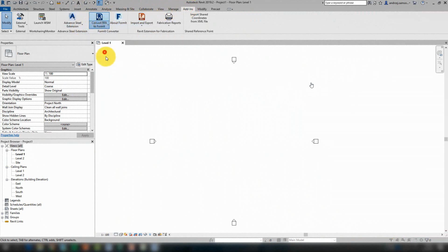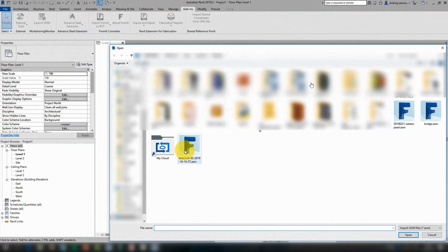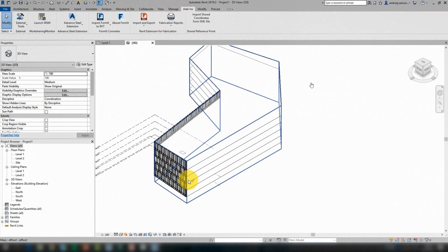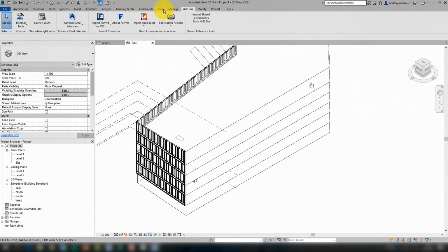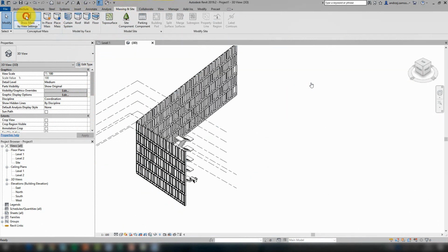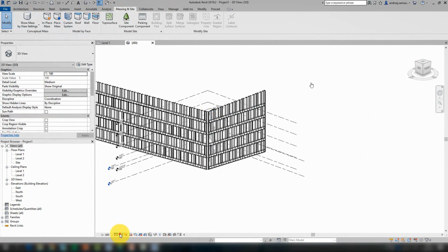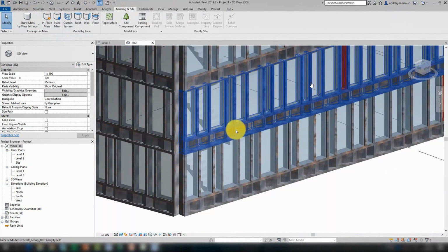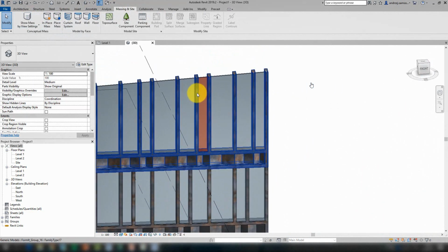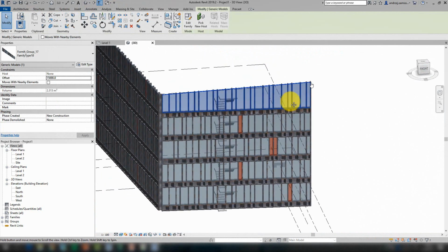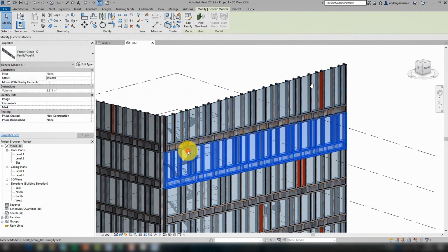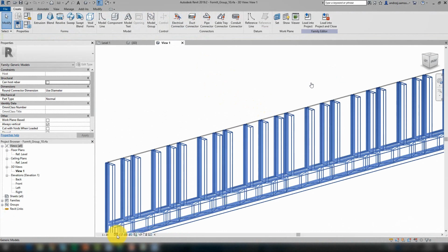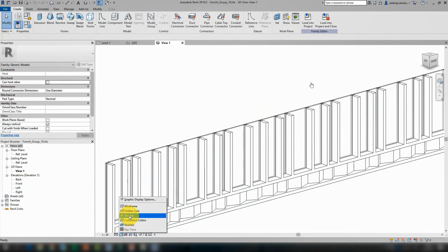So what happens now? Now I'm importing my Formit model into Revit, right? I'm going to open it, and it's bringing it here. If I turn off, for example, the visibility of my mass, because the volumetrics that was created in Formit has been brought here and saved as a mass. The families, so the facades, if I click it, you can see these are generic model families. I also have, when exporting to Revit in Formit, the possibility to select what kind of category it will be.